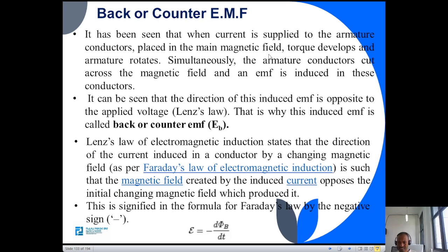So that flux is going to be a counter of the flux which is produced by induced EMF, back EMF. That is an opposite. So Faraday indicates that opposition with a minus sign. We usually keep the formula when you write the induced voltage as minus dΦ/dt. Of course, we can put N here when we want to consider any number of conductors. Anyhow, this minus indicates that it is produced by the anti-flux, produced by the main flux, in the opposite direction.